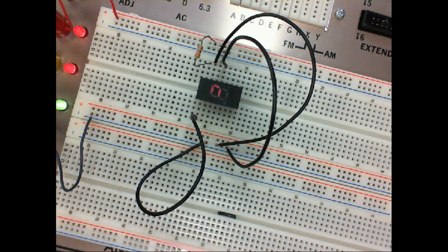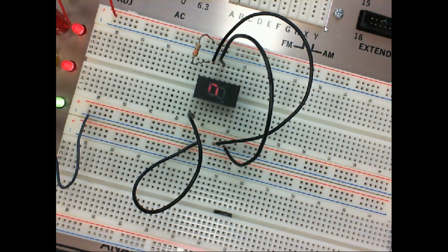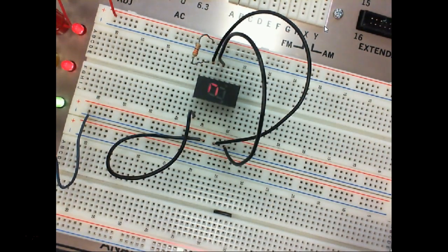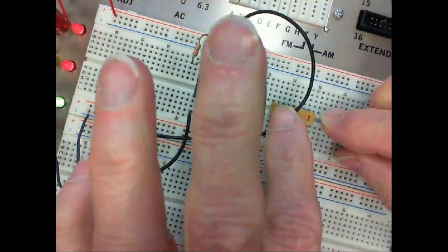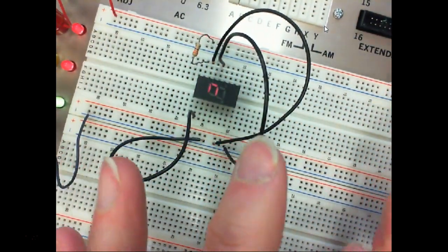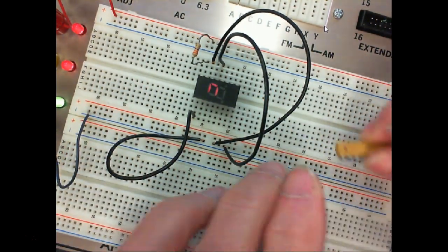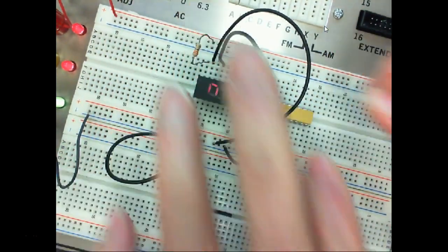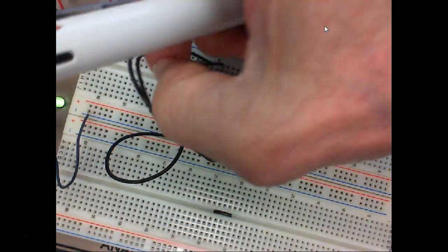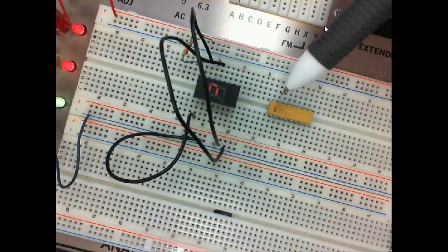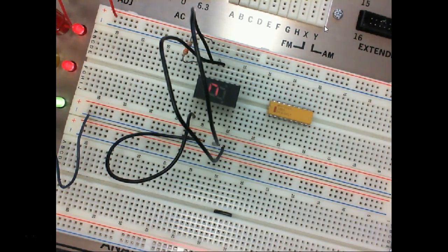Now I've seen some devices that do that because it saves a lot of money. What we're going to use, you'll run into a lot of these. Instead of me coming up here with 8 resistors, I'm going to use what is referred to as a resistor pack. It's an integrated circuit, but instead of being electronic, it's nothing but resistors. It's 330 ohms, and this uses a technique that's kind of like a color code.